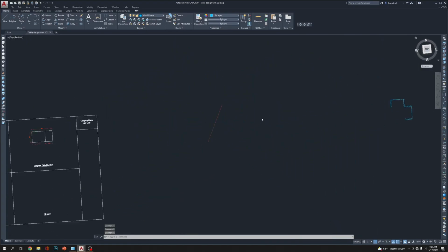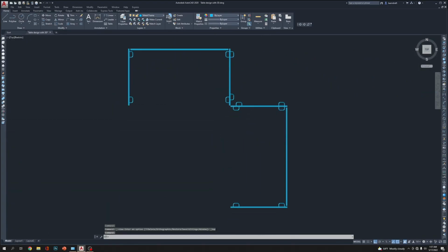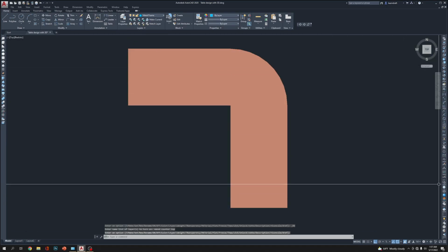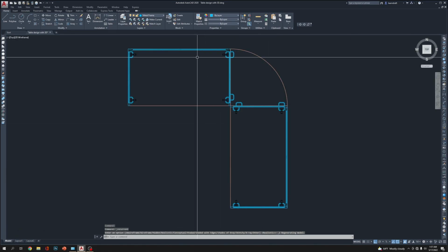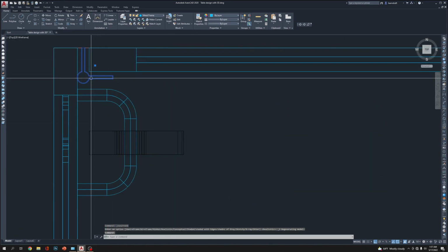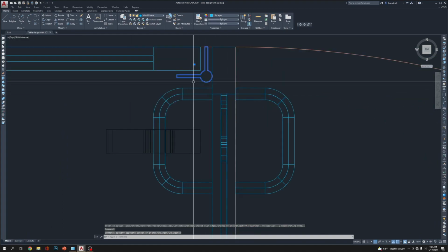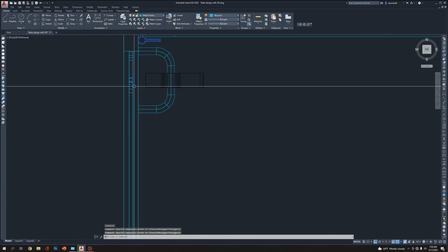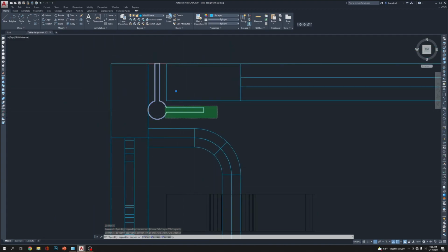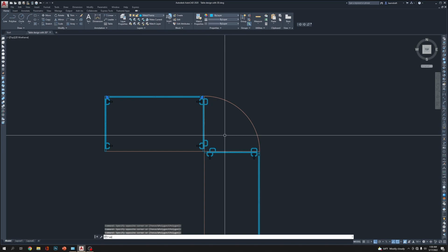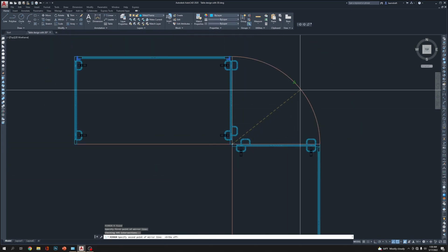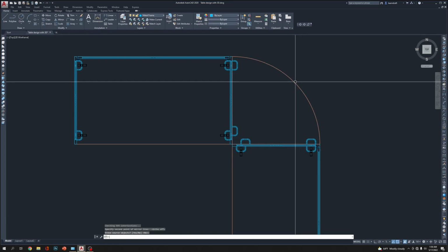The same hinge is going to go to the other side. Click here, bring the wood back, go to wireframe. Okay, select the hinges from both corners. Select like this, so I'm going to select everything because we have two. Mirror from this corner, F8, that corner, enter.